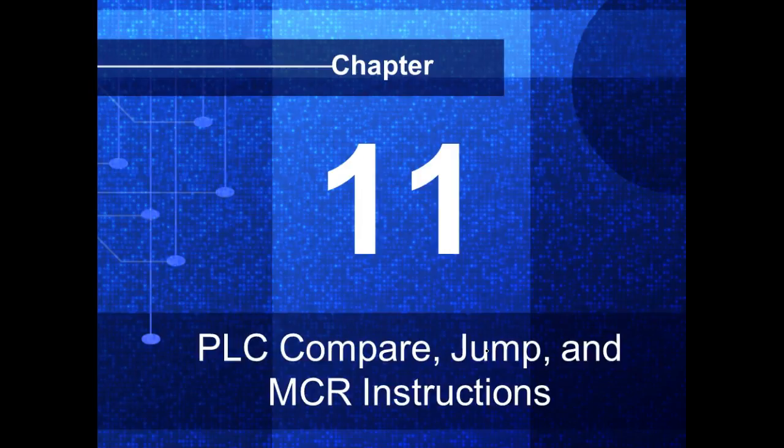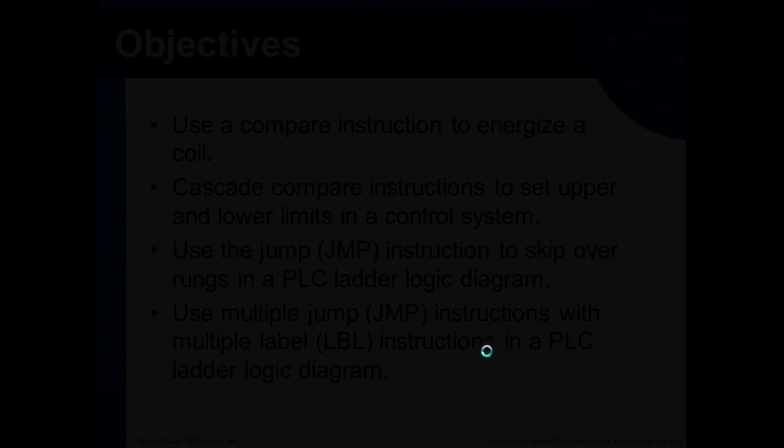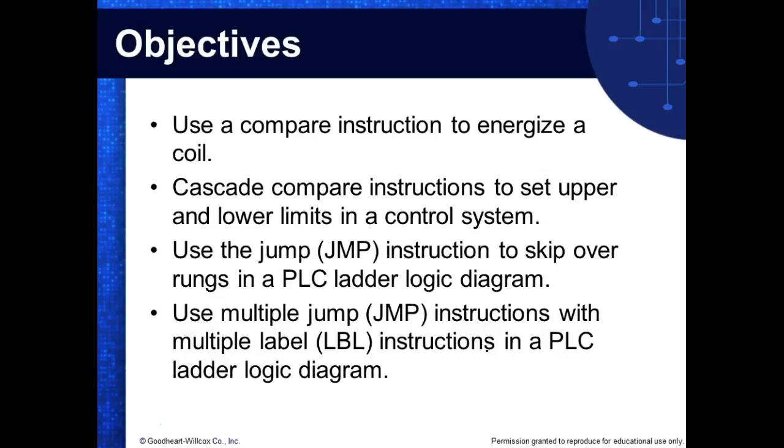So compare instructions. This is what we can do with a computer that we can't do with relay logic. Okay. This is what really gets us into some high power stuff once we add the computer capabilities. Use a compare instruction to energize a coil. We can use a compare instruction to energize a move instruction. We can use a compare instruction to energize any output instruction, right? Y'all understand that? Any output instruction.